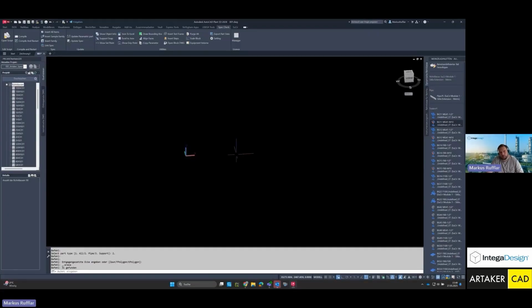Of course, with the existing Plant 3D update, you can already achieve quite a lot, but you always have to make sure that the component designation is set to parametric so that it actually updates the parametric values. There are a few issues if you haven't done that and so on. And this button is specifically there for that purpose. It always replaces the parametric components. So in other words, it really fetches the current data from the pipe class and replaces them.